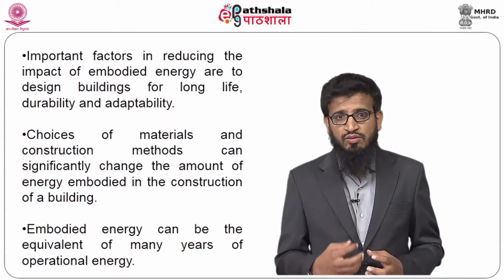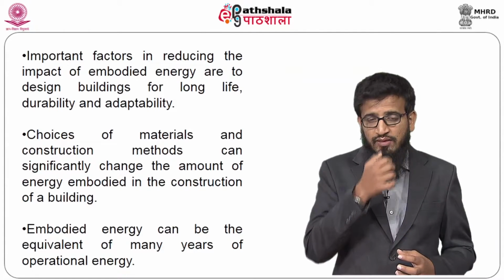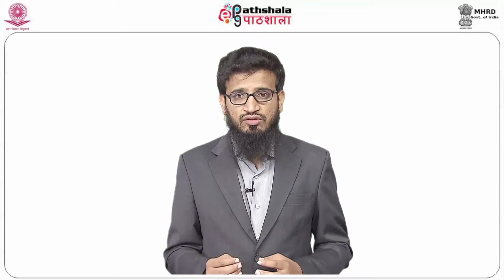What it means here is the type of materials you are picking. It is always recommended that you pick materials which are locally available. The reason is that the least amount of transportation is required, so you save a lot of energy in transportation. Also pick materials which can be recycled or reused, which means that they can be adapted later on.